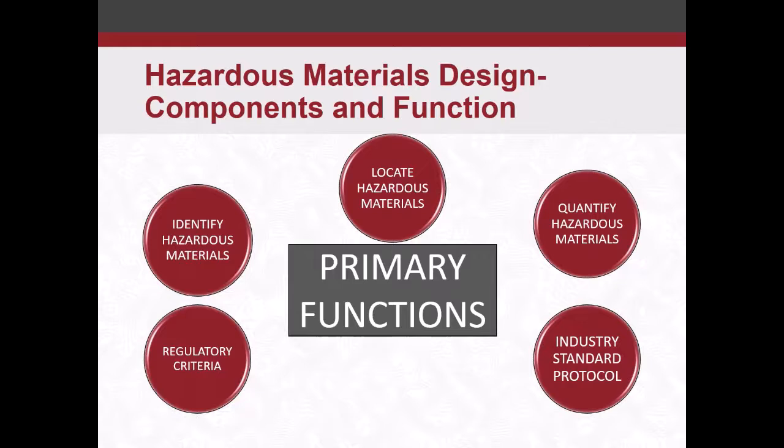And then there are other items that may not necessarily have specific regulations that dictate how to abate or remediate. For instance, a mercury containing floor system, which we'll discuss a little later. There is no set established regulatory criteria on how to do that work. So what you're looking at is past projects and past experience that showed that certain methods were useful in removing that and keeping the mercury concerns at bay. So industry standard protocol will come into play for something like that.